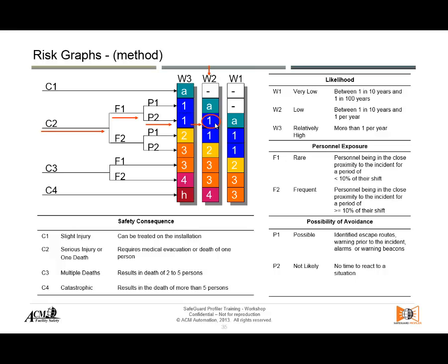And we will talk more about it, but that's the methodology. That's the methodology for the risk graph, to find out whether you need a safety implemented function or not. After you find out that there was some risk in there, and in order to cover that risk you might need a safety implemented function, you start asking yourself, well, is there already some safeguard in there? Is there some administrative procedure already in place?